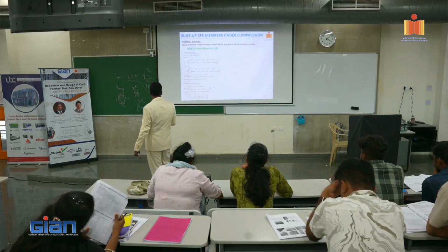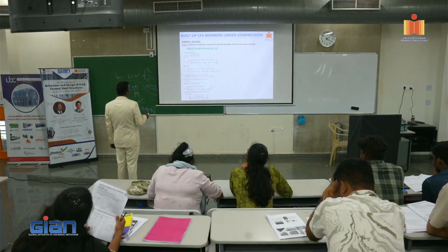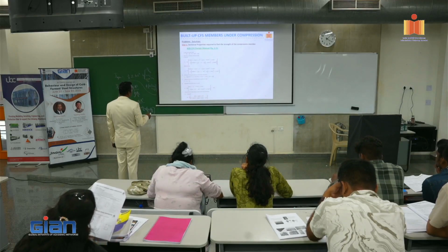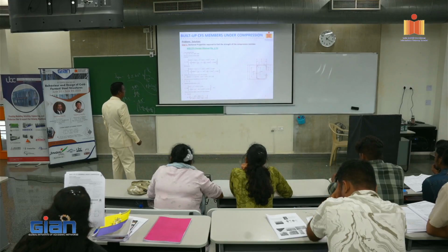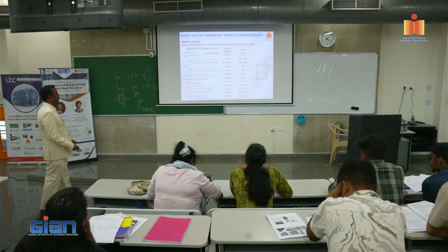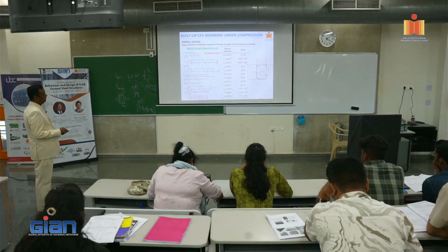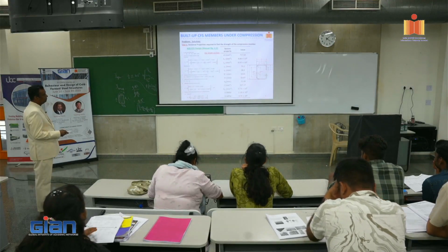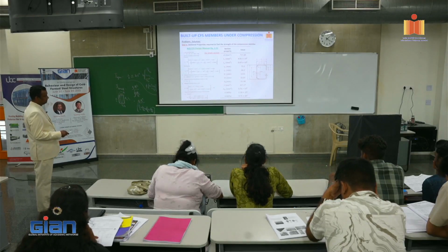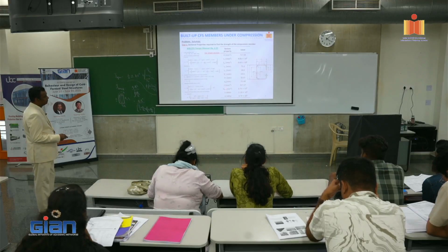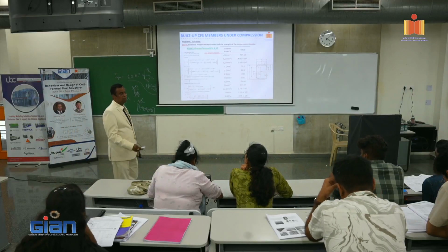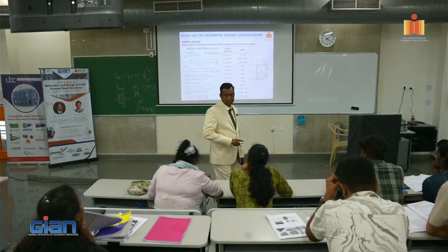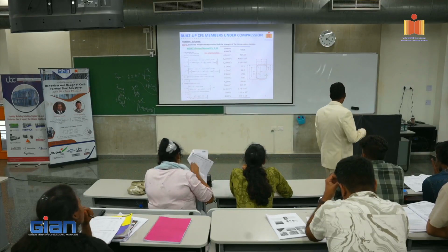Now using these section properties, right? Cross-section area, Ix, and then you have this for channel section is like this, hat section is like this, and X bar for channel, centerline, web line, all these things, moment of inertia, Iy, and there is something called M. You do all this, calculate this, and you get these properties. So A is there, Ix is there, Iy is there, Rx, Ry, X, C bar, M, all these things are defined here. X0, J is the torsional constant, 917.27, warping constant Cw is given by this one. Right, very simple, but these are all for singly symmetric cross sections. Now how do you go from here to doubly symmetric cross sections, right?